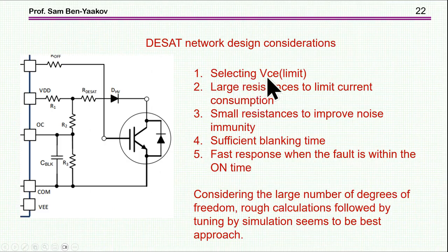First of all, we have to decide what is the voltage which is the borderline between proper and overcurrent case. And then there is a consideration that you'd like to have large resistances, not to drain the power supply, the auxiliary power supply.